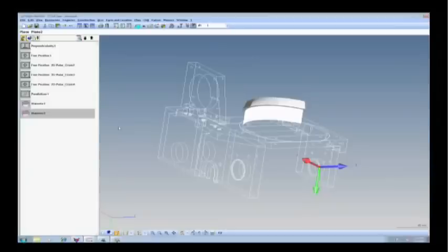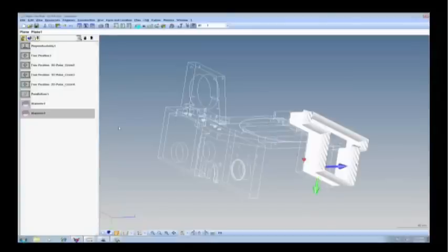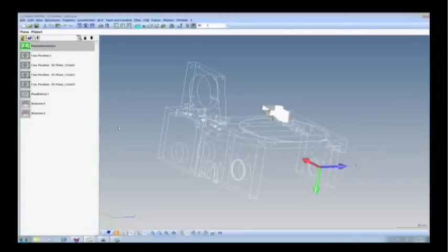Now we're running the measurement plan. Those arrows simulate the locations at which I'm actually collecting the data. The measurement plan that was created on the Faro arm, then used on the CNC CMM, is also being used now on this data that was created from the Metrotome. While that's running, I know it'll take a couple minutes, we've got a couple more questions coming in here.